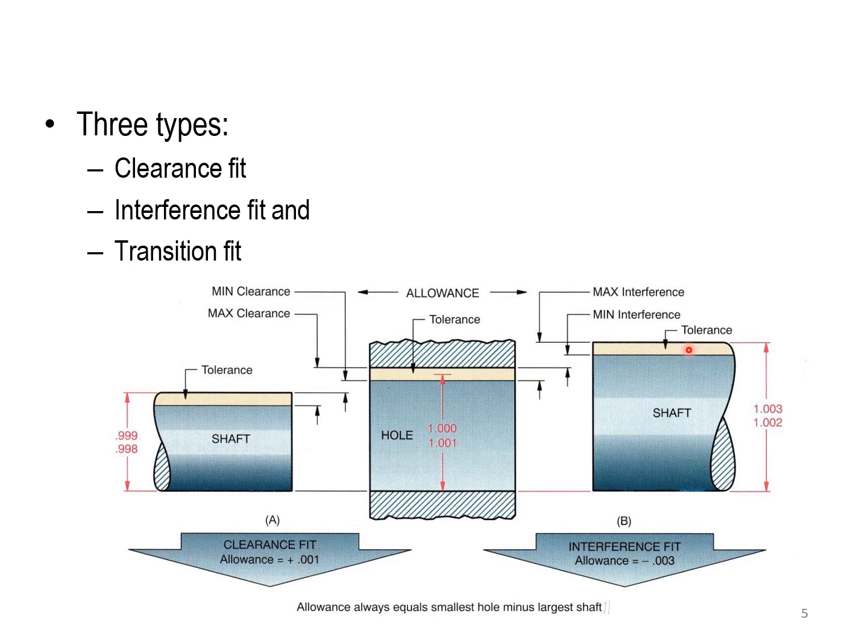If we move to the other side, the shaft is now larger than the hole diameter. In that case, we have the interference fit, where the allowance is negative 0.03 inches. So obviously, what you can see here is that this one can fit in and move loosely, while the other one is forced to fit in and then gets stuck. So you will understand that we have the maximum clearance for the hole, and the maximum and minimum interference for the shaft in the case of the interference fit. In the case of the clearance fit, only a tolerance value is applied.